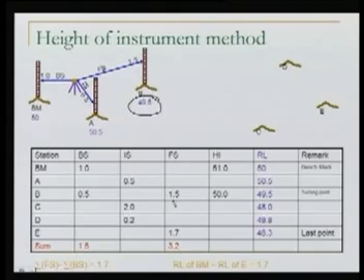51.0 minus 1.5 is 49.5 and we write it here. Okay, still don't get confused, still we have not written anything here. So we have written now this particular value and this is the RL of point B. Well, next job is, because we need to find the RLs of C, D and E also.